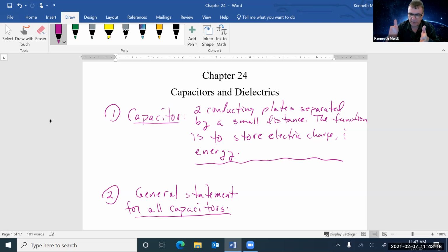The capacitance is not the same as charge, right? Charge is a number of coulombs. Capacitance, though, needs to be proportional to that. When you can put a lot of charge on something, then you have a high capacitance. If you have capacitor plates about the size of dimes, two little pieces of metal, there's a certain amount of charge you're going to be able to put on there. If you have big metal garbage can lids, 2.5 feet across, you're going to be able to put more charge on something like that because of the geometry of the conductor.